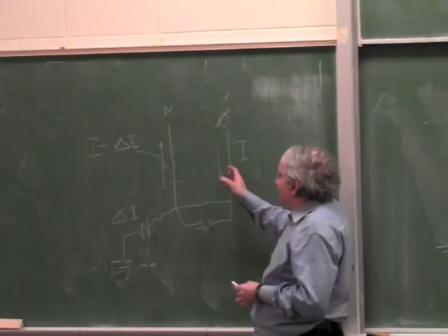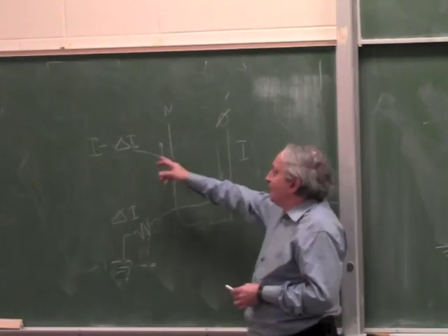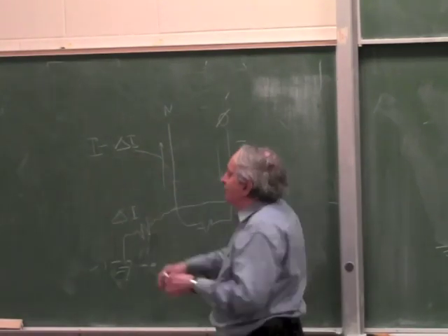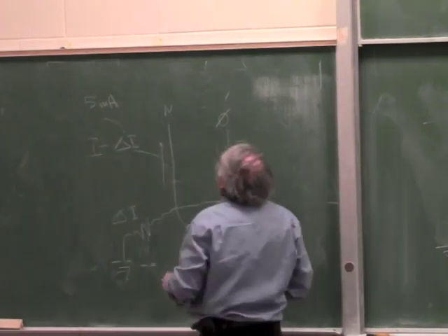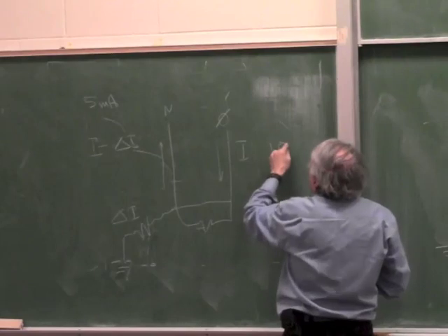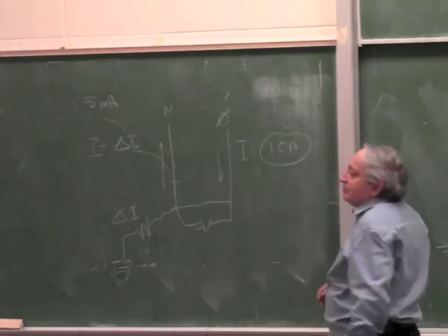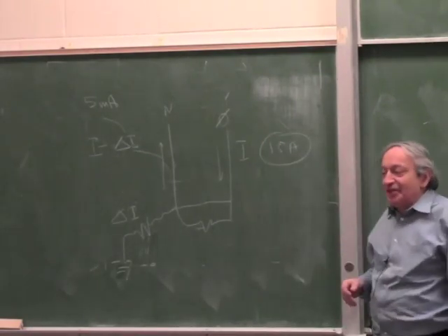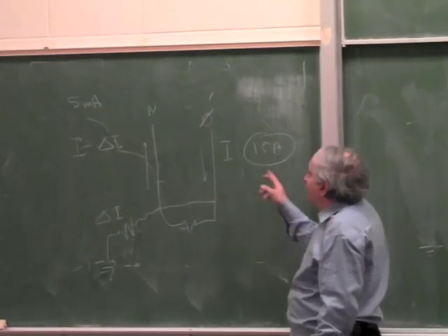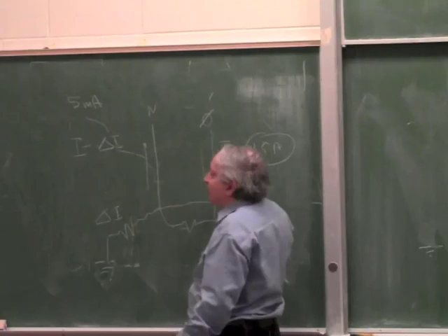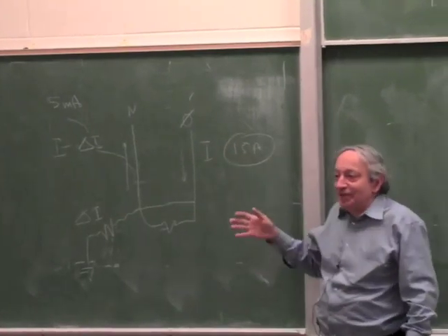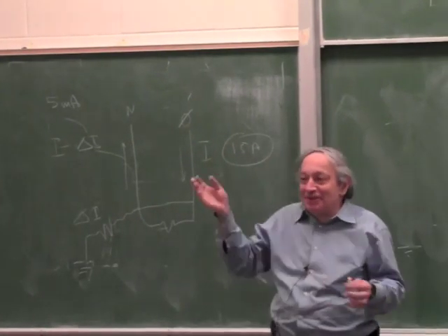So how does it physically work? This is a very small difference. Typically the GFIs are set for 5 milliamps. That's the code. And this is actually 15 amp, because the outlet will give you 15 amps. So how can it detect a 5 milliamp leakage on a 15 amp current for $10? Because it's a very simple thing. You can buy it in any hardware store.